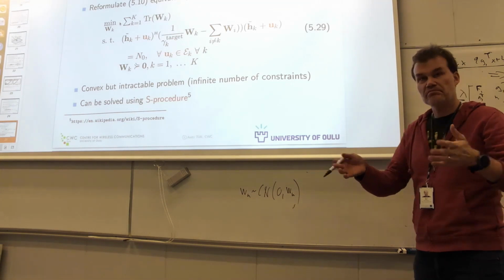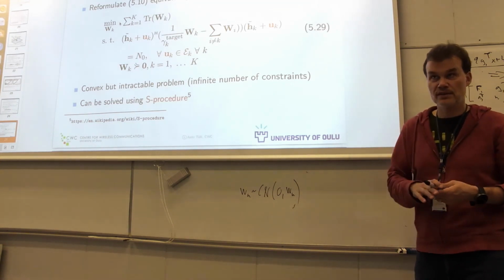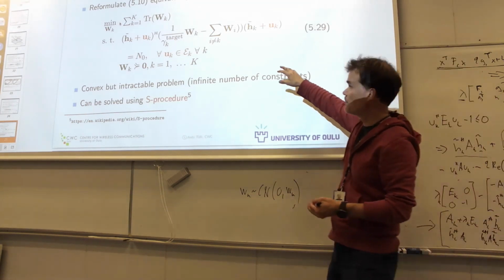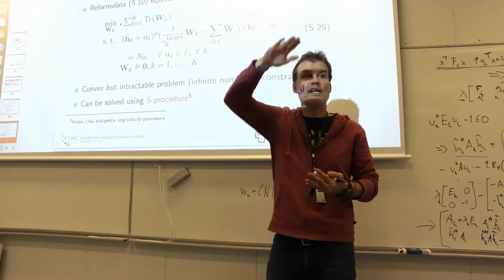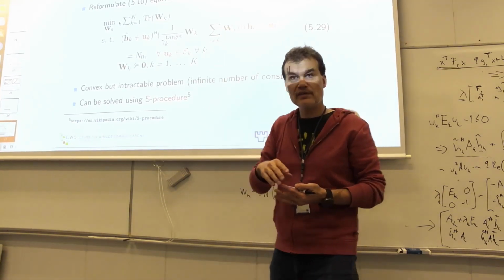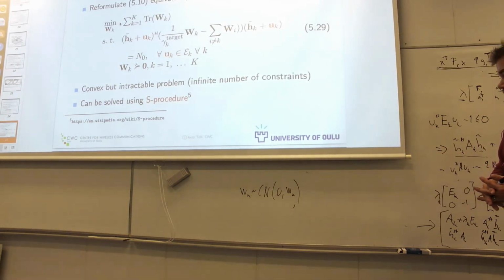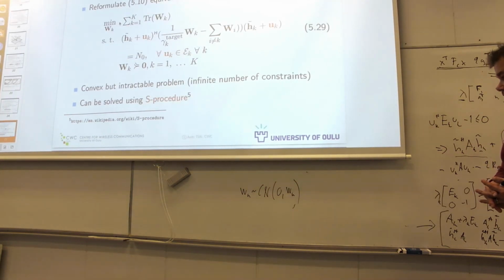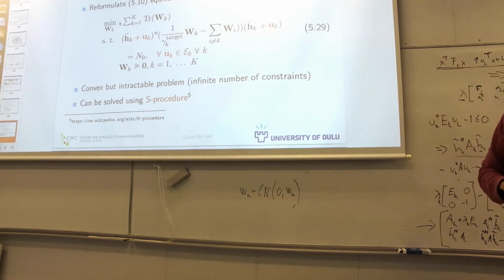And then you generate 100 of those and choose the best. But for that beamformer, the SINR does not necessarily hold, so you have to scale it up. You just multiply it with some extra power. That actually will lead to some power loss.